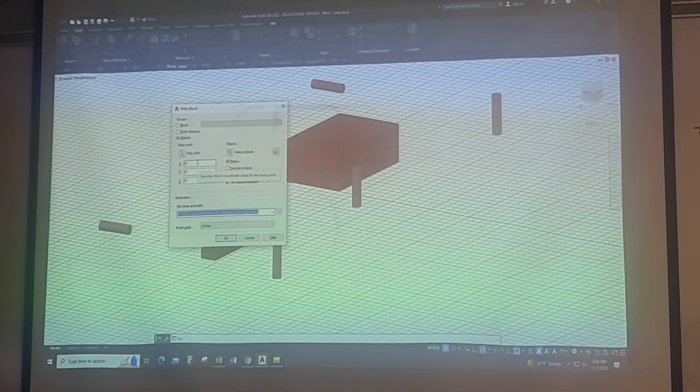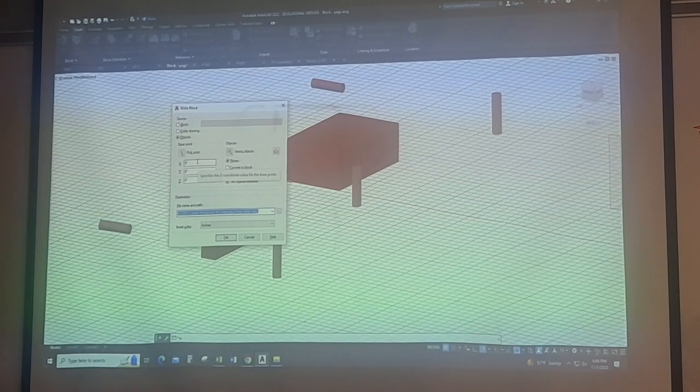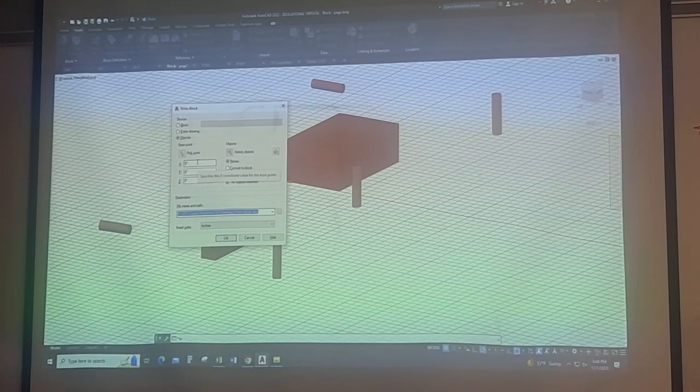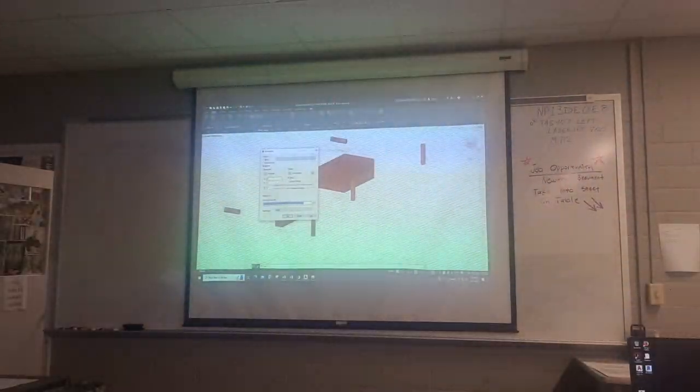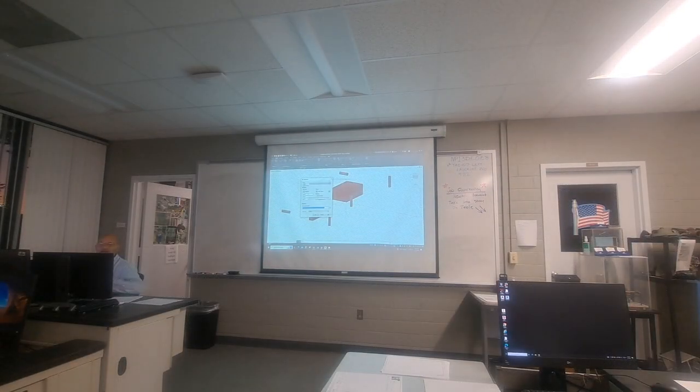Had I not done that, your better path would have been to draw that first object, the square piece with the peg sticking up, based on 0, 0, and then draw that second part 1/2 inch higher. That way, when you put those together in that assembly drawing, it would have dropped right into place, without having to move it up or adjust it 1/2 inch.